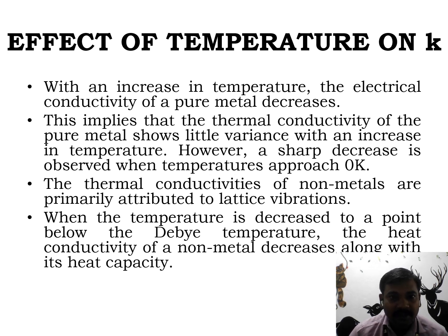Then the effect of temperature on thermal conductivity. These are all very important basic concepts. With an increase in temperature, the electrical conductivity of a pure metal decreases. This implies that the thermal conductivity of a pure metal shows little variance with an increase in temperature. However, a sharp decrease is observed when the temperature approaches 0 Kelvin. The thermal conductivity of non-metals is primarily attributed to lattice vibrations, and as the temperature decreases to a point below the Debye temperature, the heat conductivity of a non-metal decreases along with its heat capacity.